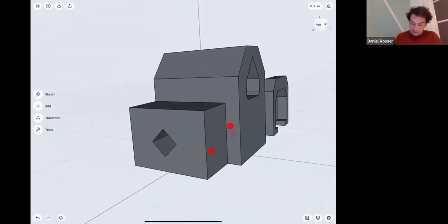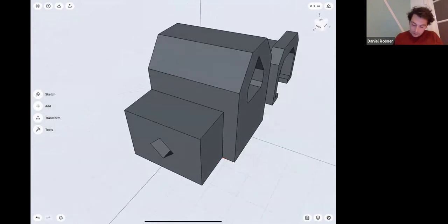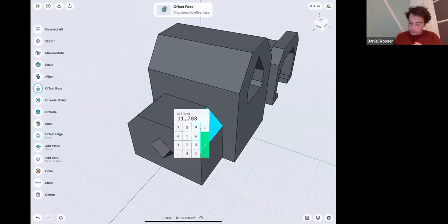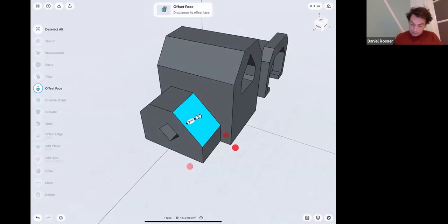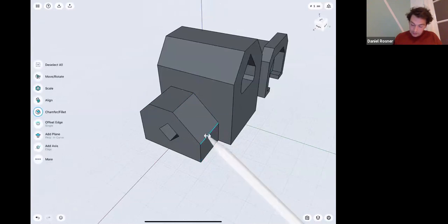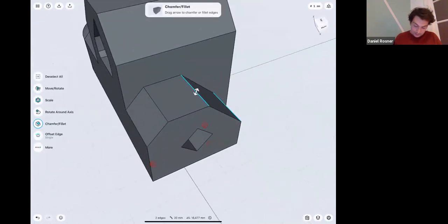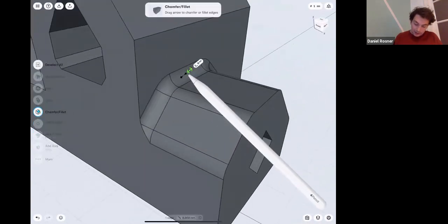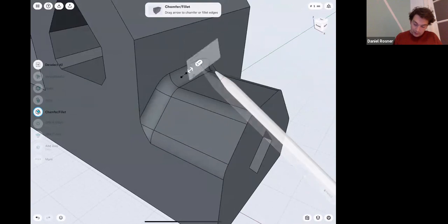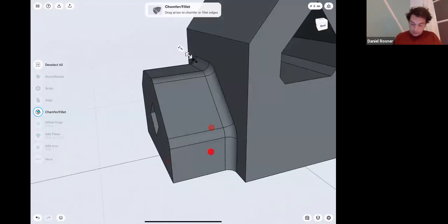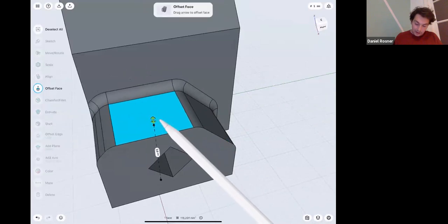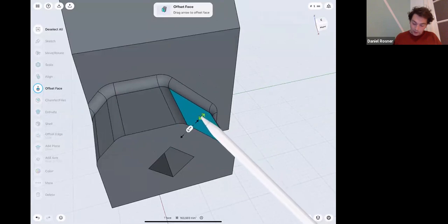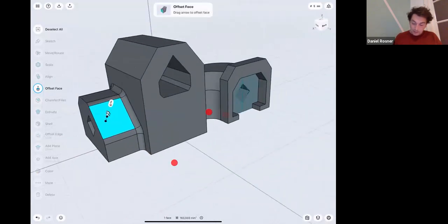So now what's left is to add those chamfers and fillets. And I'm not going to do all of them because we are running out of time. I'm just going to show you how you can precisely dimension your chamfers and add fillets as well. I'm going to select a couple of edges here. And notice that the app actually notices that your fillets are continuous and you don't have to select all of the edges. And direct modeling makes it available that all of the features are saved. And while you modify these faces, it will remember that those fillets should be there.